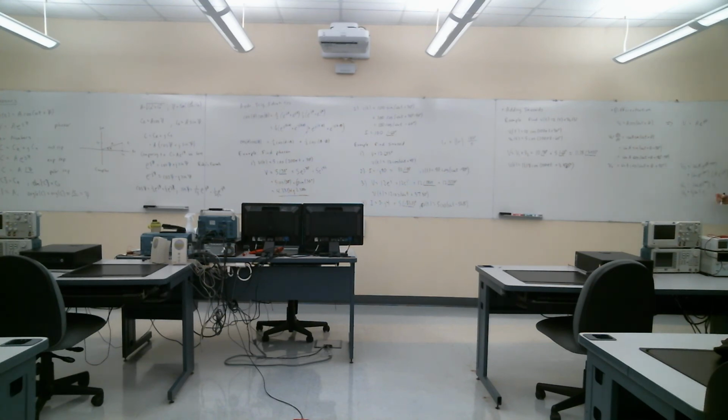So in order to differentiate in the phasor domain, it's trivial when I'm dealing with sinusoids. I just multiply by j omega 0. The omega 0 changes the amplitude I get from the differentiation. And then the j is a 90-degree phase shift that I also get from the differentiation.